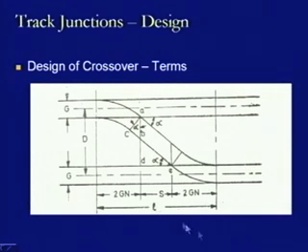Then further, in this case the things are clearly shown. This is one track, this is another track with gauge G, and this is the center line, these are at a distance capital D. Now, we have a reverse curve here, then there is a straight portion in between, and then we again have a curve on this side, that is why this is a reverse curve. Now, this straight portion starts from this to this one. If we take the projection of this one, then this is S, and then this is a curved section.